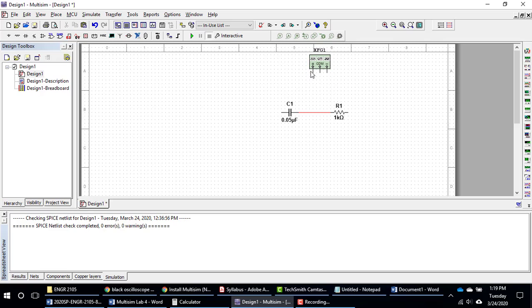And I do that by connecting the positive to one side. So if I click right there, I can make a corner. And my common comes to the other side. And I'm telling you right now that I'm setting this up incorrectly. But I'll tell you why in a moment. So this looks like a circuit that is connected to my signal generator in Multisim.